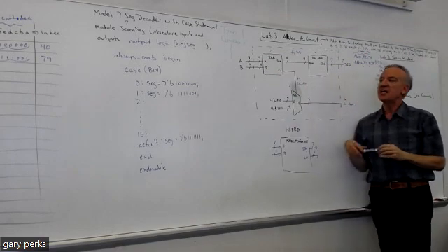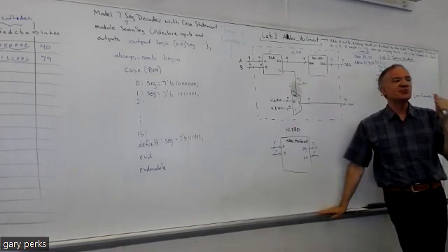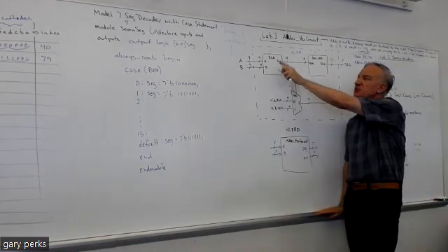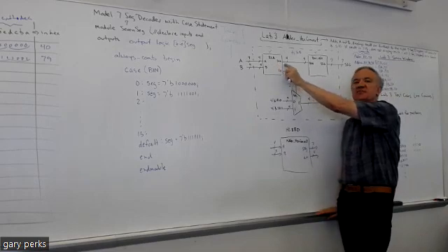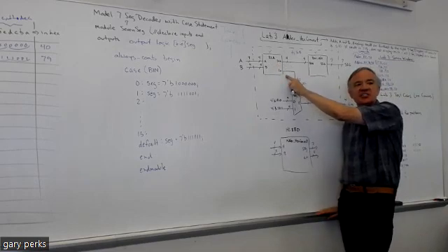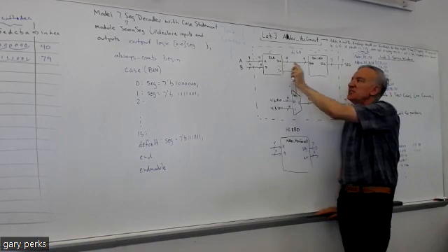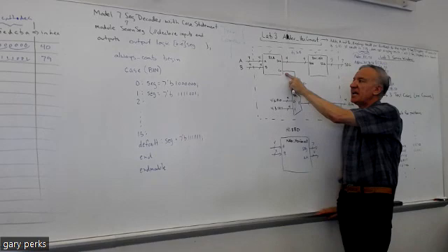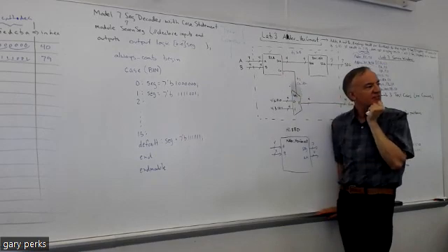So, when does the carry out of this RCA change from a 0 to a 1? When it gets higher, right, exactly. When the addition result is 15 or less, the carry out is going to be 0, right? It's only when the addition result is greater than 15 that the carry out will be 1.